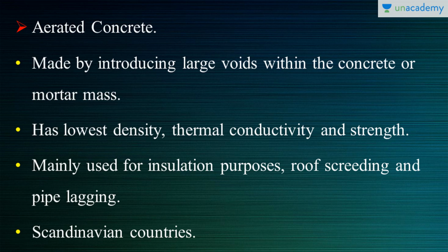All right. So that means that there will be two types of voids present inside: the introduced voids and also the extremely fine voids due to the air entrainment. So this has to be distinguished, and also these voids should not come in contact. If they come in contact, internal stresses will develop, which increase the porosity of the concrete, which ultimately results in the lowering of the strength.